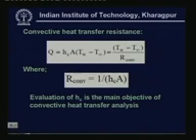And the major problem in all convective heat transfer problems, the way it has developed, is the estimation of the heat transfer coefficient. So, you can see that almost the entire literature on convective heat transfer is devoted to evaluation of the heat transfer coefficient, because once you know the heat transfer coefficient, you can find out the heat transfer rate by multiplying that into temperature difference and surface area.